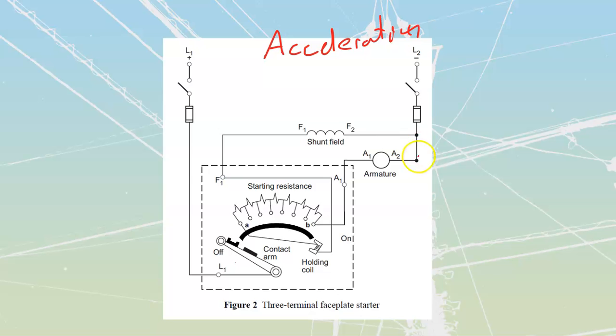The other thing that I'm going to take a look at is the fact that my armature is connected in series with a whole pile of resistances going across here. Those resistances are going to allow me to drop, when I start out over here, lots of resistance. So I'm going to have lots of resistance initially inserted. I is equal to E over top of R. So initially I'm going to have a large amount of resistance, but then I'm going to start dropping that resistance, which is going to allow my current to go up through here. If I were to just throw this thing in, if I were to make connection across from here to here initially, we would have too big of an inrush on our system. We're attenuating that with this.